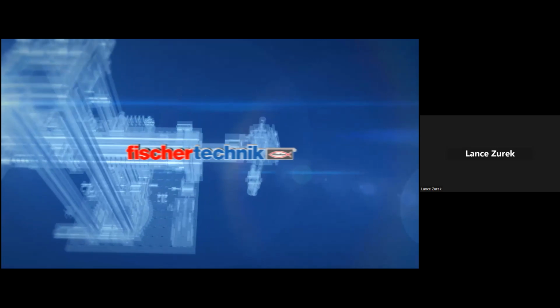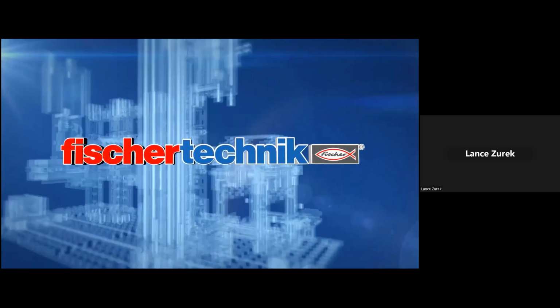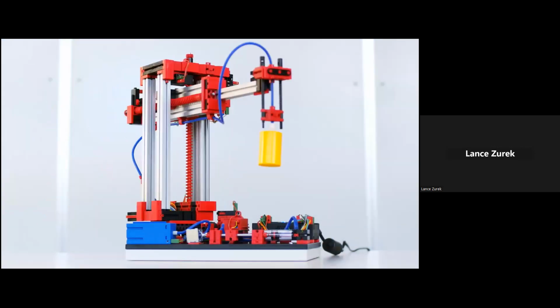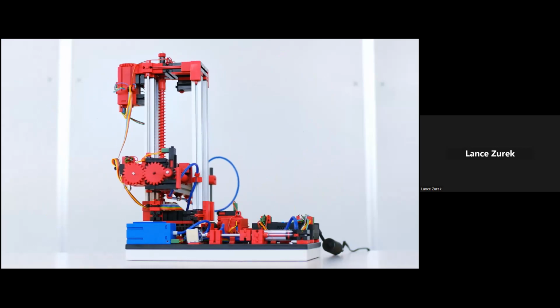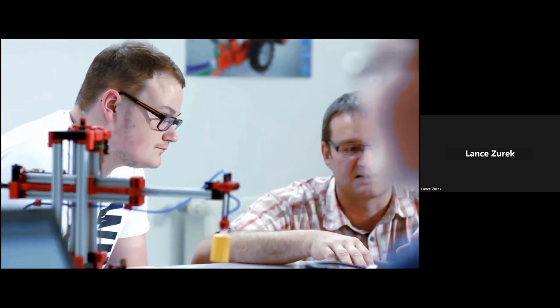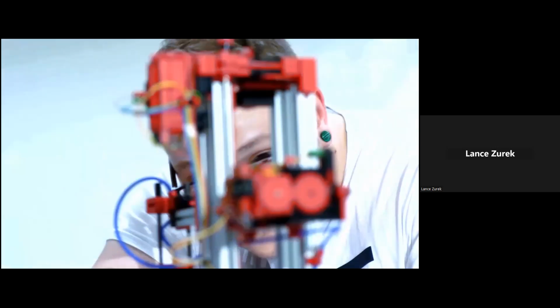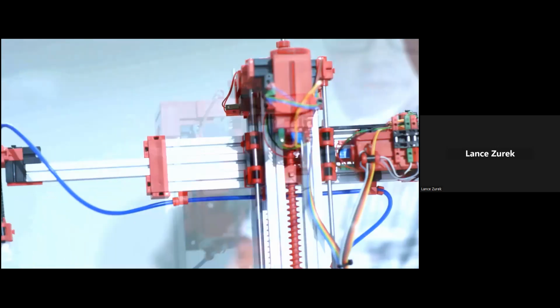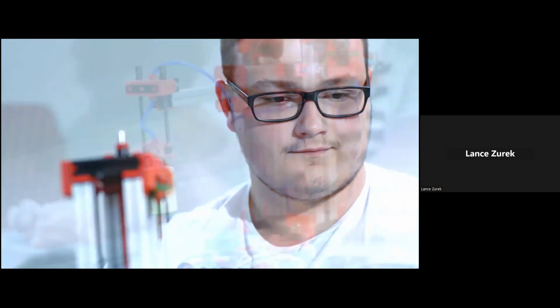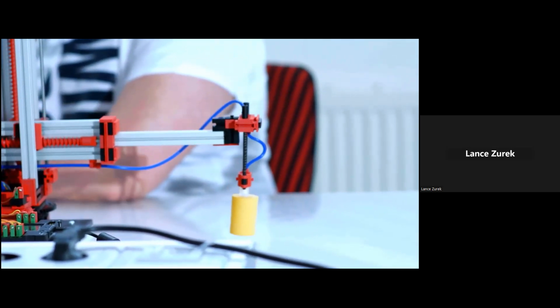Now, as you're going to see in this video, the vacuum gripper robot is a 3-axis robotic model with a vacuum gripping device. The model is designed to precisely pick up and position workpieces in 3-dimensional space. The model itself includes 3 encoder motors, 3 push-button limit switches, a vacuum suction device, a compressor, which is the blue brick component that you'll see in the video, and a solenoid valve.